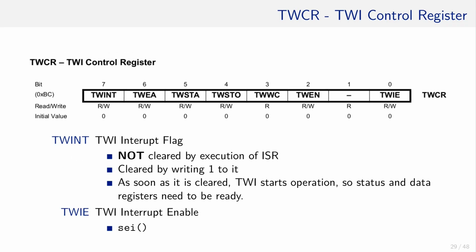Okay, here we have the control register, which determines what is being sent out, to what the status register reacts. The first two bits are the TWINT and TWIE bit. TWINT is the interrupt flag, and it is set if the I2C hardware is ready to process the next byte. That can be after, for instance, the start condition has been sent successfully or a data byte is transferred. If global interrupts and the TWIE are set, an interrupt request is issued.